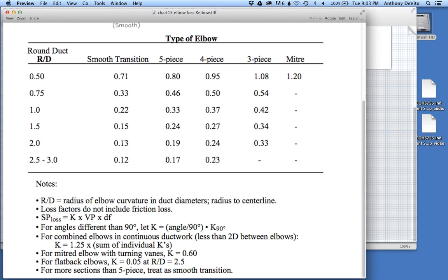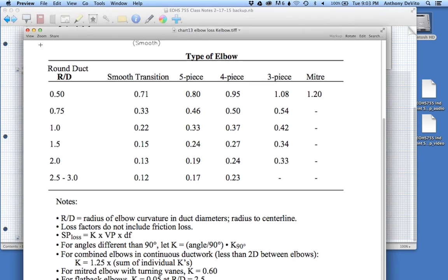And if you have several elbows, like in that first design, we had 3 elbows, one turned up, one turned across, one turned back down for the filter, going into the filter. Then each one of those turns would produce a loss like that. Okay, that's how we'd calculate that. So we're slowly starting to build our tools for being able to design this kind of system.